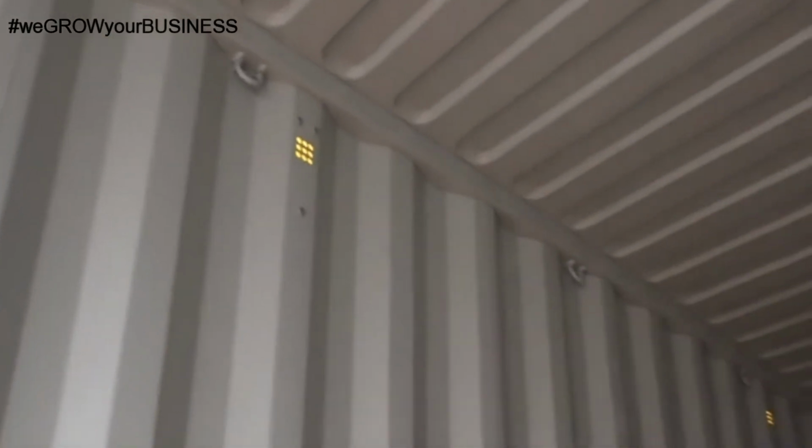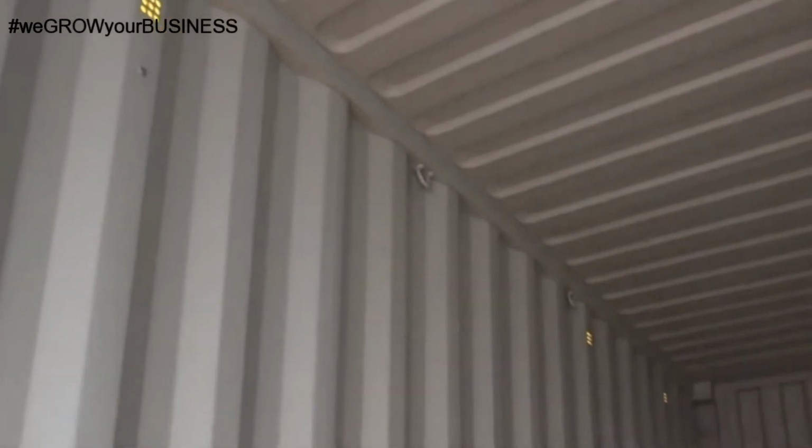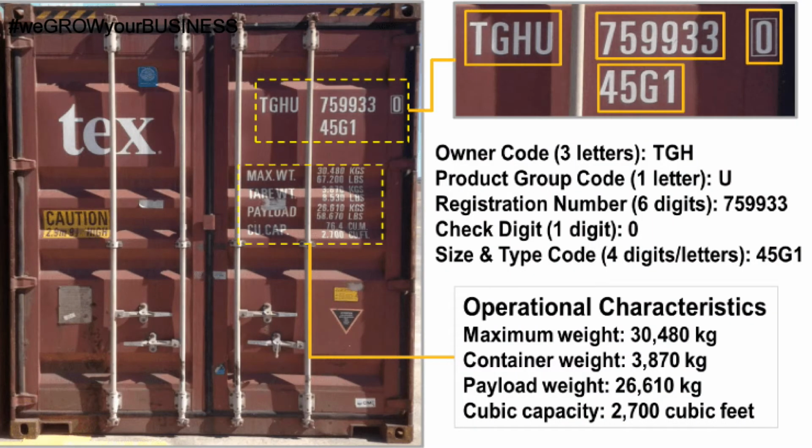Almost all cargo containers are built in accordance with the specification requirements of TIR, CCC agreements and the International Convention for Safe Containers. Lashing rings are available on the inner side of the containers to secure your goods and provide more safety while being transported. The payload details are indicated on the side or maybe the rear door of the dry containers. However, the rules and regulations on maximum weight conditions may differ from country to country based on VGM, which stands for Verified Gross Mass.